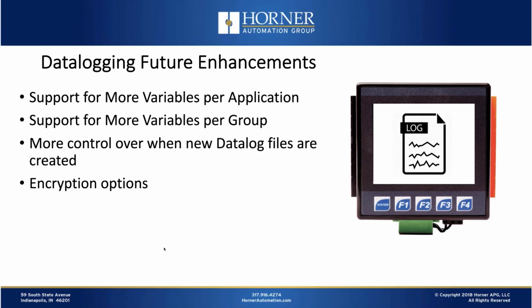So that's why we said, hey, if you're logging data every second, we're going to create a new file every hour. Maybe if you're logging data every few minutes, we will create a new file every day. And even if you're logging on an event basis through a triggered read only, we're still creating a new data file every day, which some people don't like. Now you can overcome that by kind of rolling your own data logging by using removable memory function blocks, but that's a lot more work. So we will provide some additional control in the future to give customers, specifically those who are a little more power users, the ability to precisely control when a new file is created.